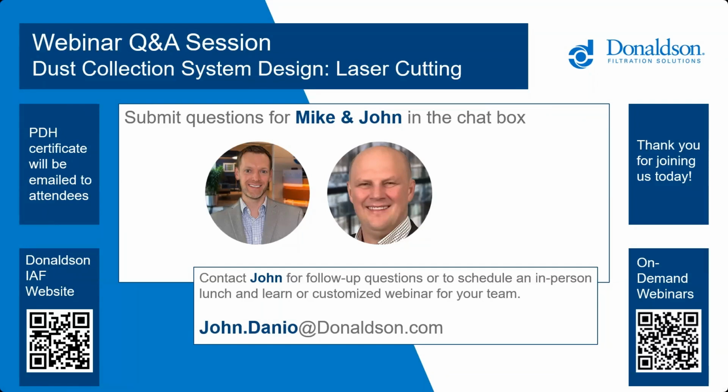Well, and the result of that would be fire, right? Every OEM wants to avoid fires, and occasionally, we will hear of an issue out in the field where a system wasn't set up right and results in a fire, and everybody wants to avoid that and the repercussions of a fire. The other thing we've heard recently, Mike, as well, is with these higher powered laser systems, if you don't have a well enough designed dust collection system, it will interfere with the quality of the cutting and the laser itself, as that particulate can interfere with the beams. Yep, correct.